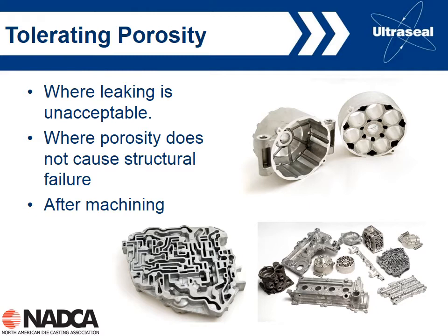And so this is when I might think about impregnation, or at least enter the discussion up front when I'm starting to design the casting and the die. Generally, the impregnation material doesn't impact mechanical properties, so it can't help with a structural casting. By reducing the porosity by impregnation, you're not going to have an impact on mechanical properties, but obviously what you are going to impact is leaking. And so you can think about impregnation when you've got a casting where leaking is an issue.